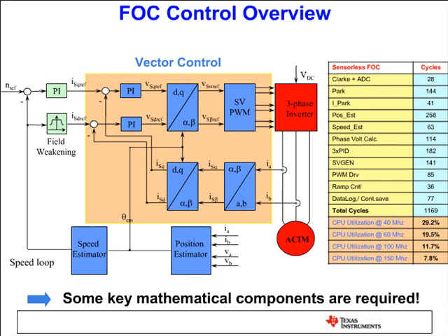In our applications, we mostly use a sliding mode observer for PM type of motors. So in sensorless control, instead of using an encoder, we use a mathematically intensive algorithm which uses current and voltage information, calculates flux and back EMF, and then estimates the position of the rotor. And we feed this position information to the transformation matrices. And again, we estimate the speed using this position information.